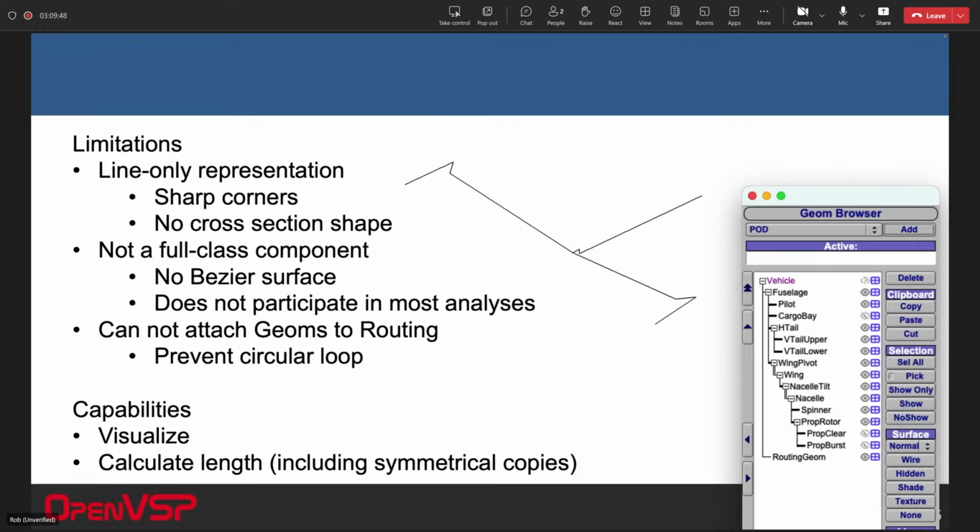And you'd be able to take that length calculation and get at least a first cut mass properties calculation. If it's pneumatics and you're doing a loss calculation, you'd know the length of that line, so you'd be able to do that loss calculation. Again, if it's wiring and you're doing a resistance calculation, you know the gauge of your wire, you'd be able to then figure out the resistance of that wire. So all those analyses start with length, and we're really just sort of giving you enough to get started.